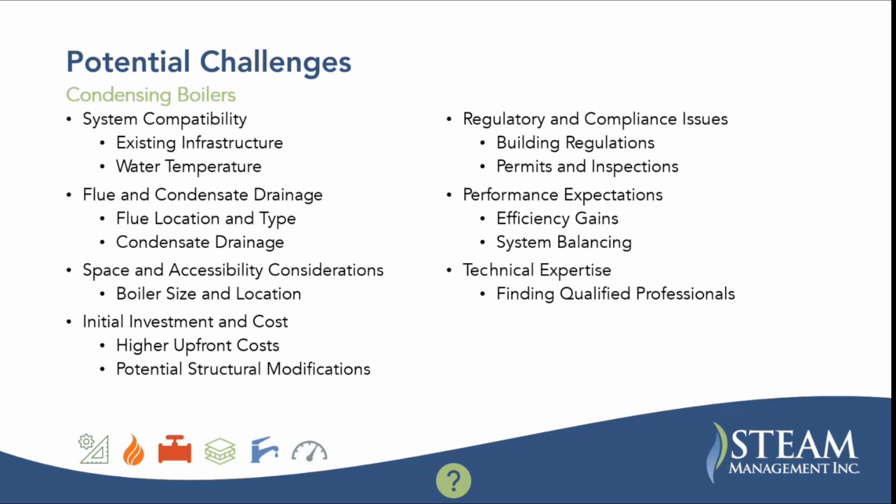One thing to note there, if you're familiar with primary-secondary variable configurations on the hot water system, usually you have a constantly flowing primary loop, and then the secondary loop pulls some water off of that to send it out to the building loads or the process loads or whatever. This is usually for a heating application. When you think about the return temperature being low, if you have that primary loop, you are blending some portion of that loop with the return water.